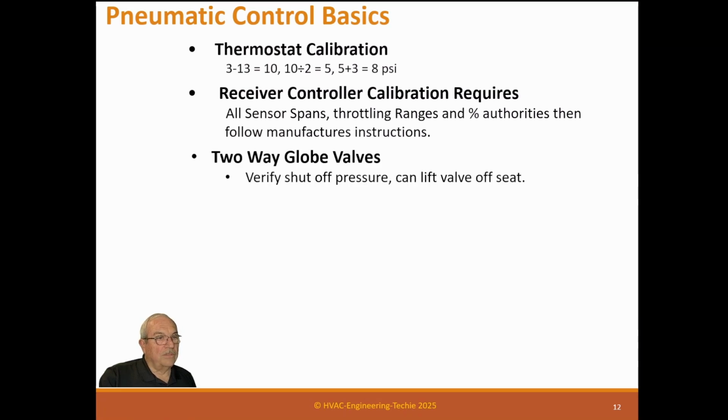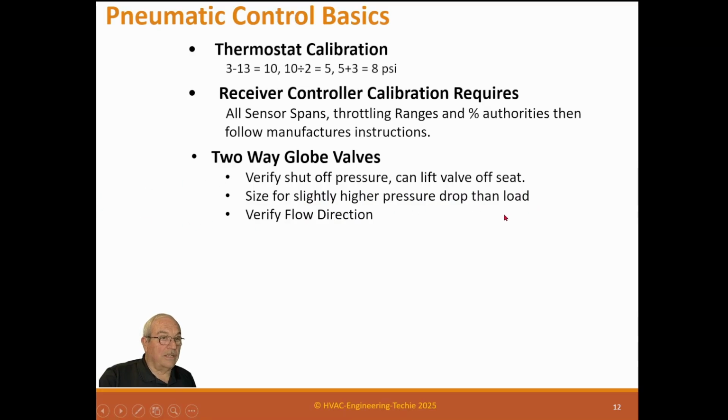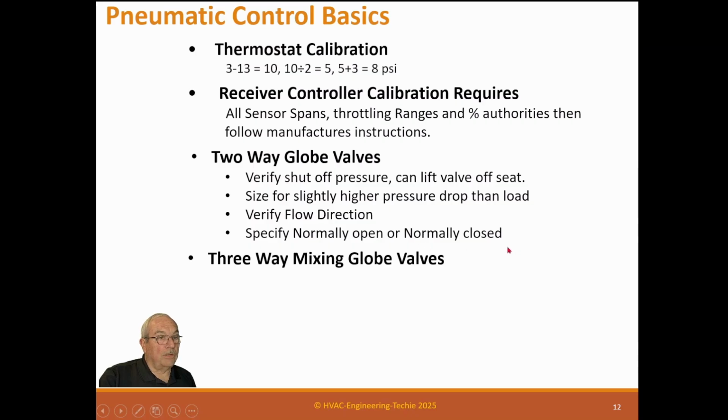Two-way globe valves. Verify the shutoff pressure that can lift the valve off the seat. Remember that if the fluid pressure is high, it can overcome the spring. It can actually lift the valve. Size for slightly higher pressure drop than the load, just like any other valve. Verify flow direction. Specify normally open or normally closed.